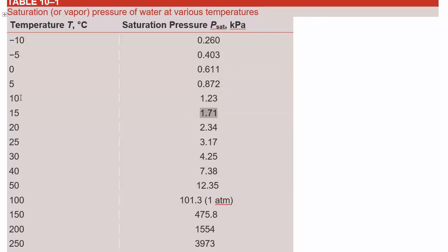But if the temperature goes to 10 or below, then there's too much partial pressure of water. There's too much water evaporated, and it's going to start condensing. Less of it would be in the air in equilibrium. The lower we go, the more of a difference between the partial pressure and the current vapor pressure, and the faster it's going to start condensing.